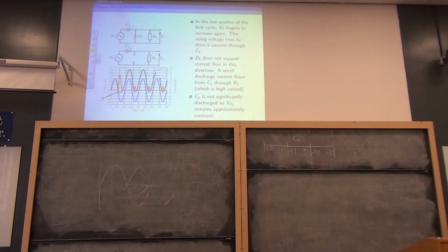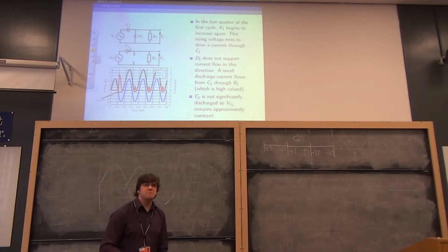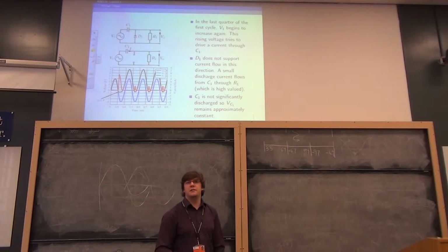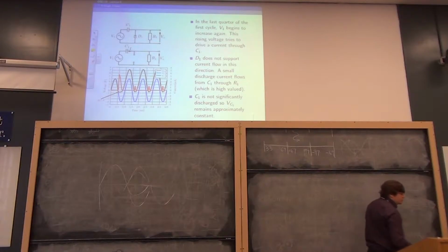So it's important that the diode stops conducting then, and it's important that R is large, because if R wasn't large, it would perform the same function as the diode, more or less, in the sense that you'd have a large current flowing through R, charging and discharging the capacitor every half cycle. And after a half cycle or two, we'd reach a steady state in which there was no clamping. You just have a high pass filter with a diode that did not do a lot. The question of R and C, the time constant of R and C, is critical to making this circuit go.